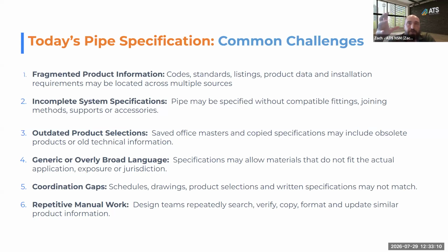Another part that we heard from the manufacturers, a big concern is products that may have passed, say, a CSA standard, but they're referencing a standard from 10 years ago and have not kept up to date. So that is a significant cause for concern and always worth double checking and making sure that your specs are current and the manufacturer submittal that you're reviewing is current.